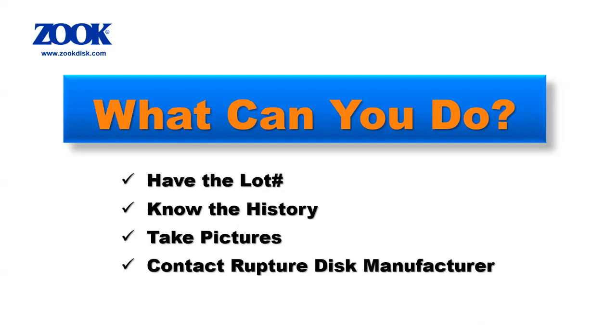What else? The installation history at hand. Is this a new or existing installation? How long has the disk been installed? Have any of the process conditions changed? Do you have similar issues in the past, or is it specific to this recent shipment or product? Take plenty of pictures: the disk, holder, flange setup, upstream and downstream. All this information builds the picture in diagnosing the problem and finding an engineering solution.